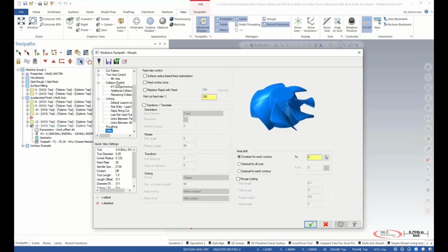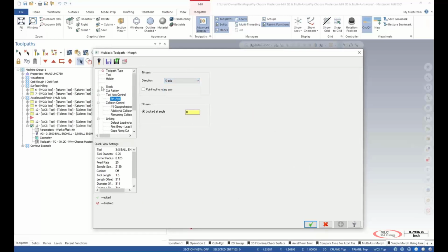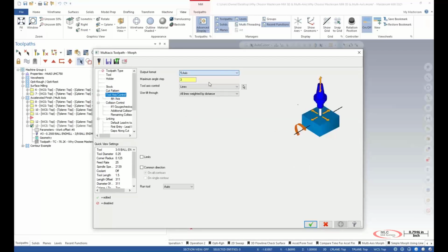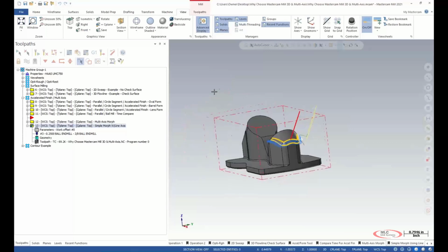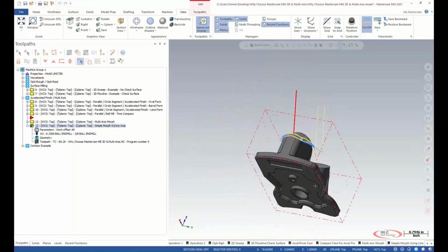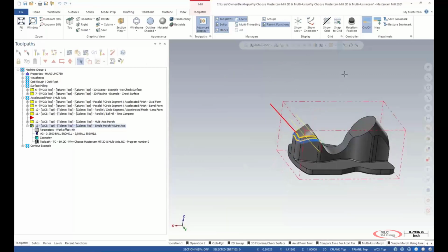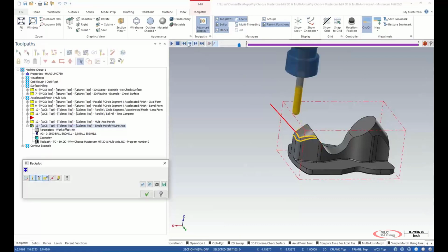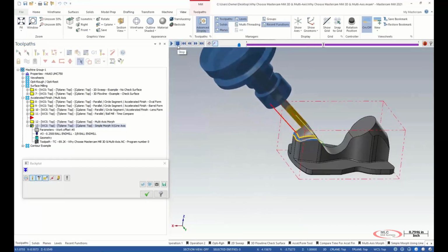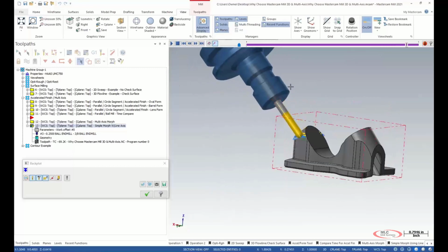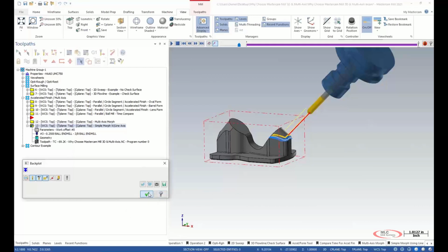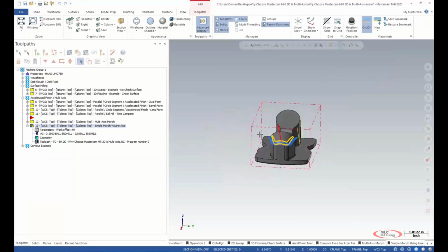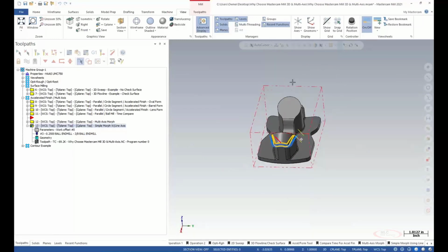If we put it in the 5-axis here, let me see, axis control, 5-axis, and let's get that nice tilt that we want. There we go. Now, what I want to display when you do follow your line like this, on the point, we actually pivoted around that pivot point there, whereas when we drive it to a line, this tool will stay stationary. So in this case, you still will have a 4-axis operation, just with the way this machine tilts. We would actually have to have the part running this way, almost like we were reading an A-axis to flip around.